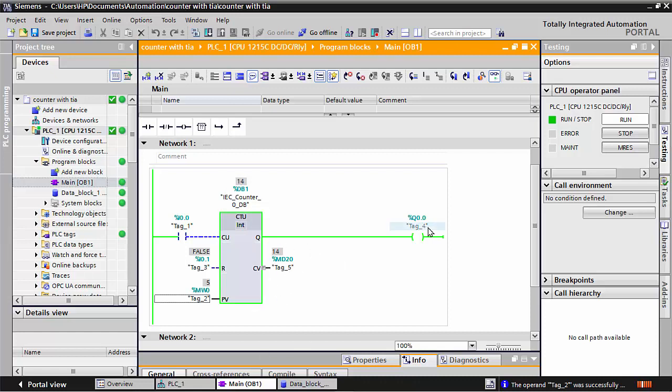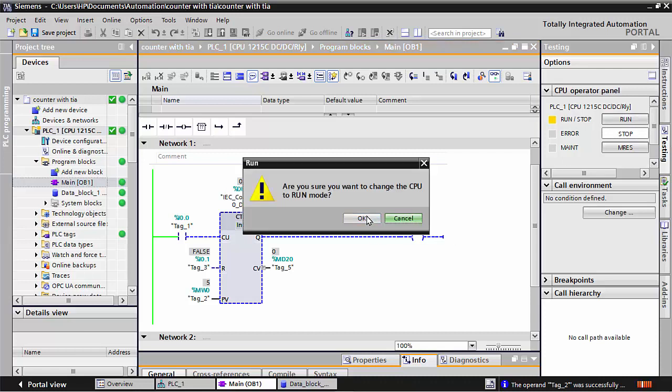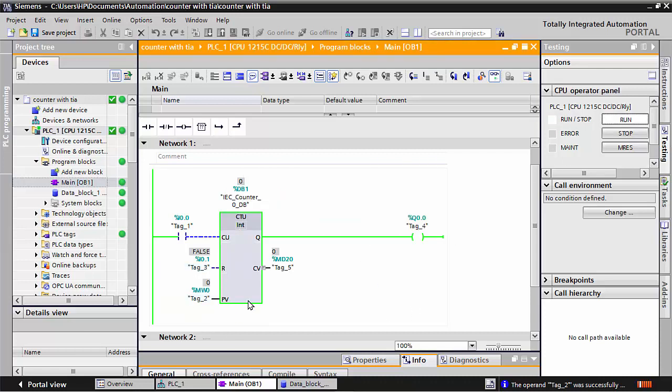This will be shown in your data register, and when you would like to reset this data register, you can give it the I0.1 address. This will go to the 0 condition. But in this system, this MW0 is not a latch data register. When your power goes, this will stop. See, your data goes to 0.